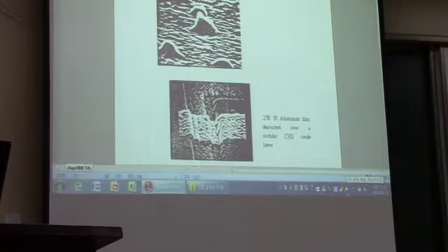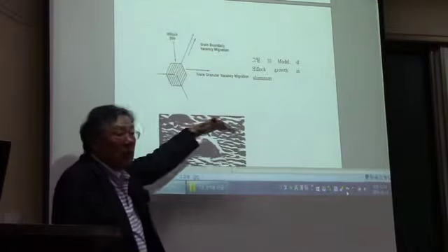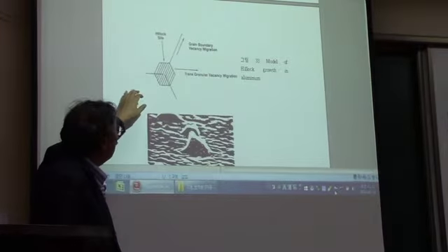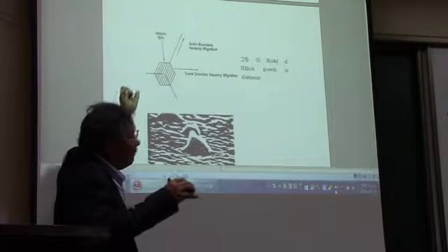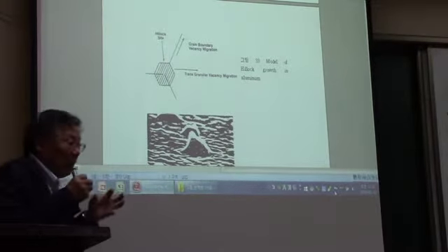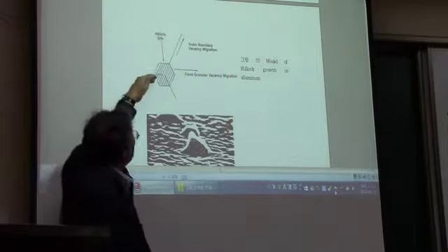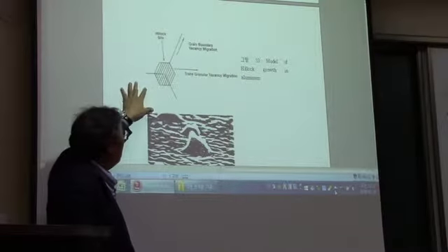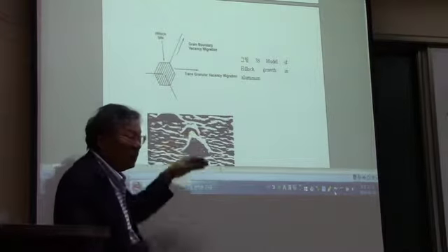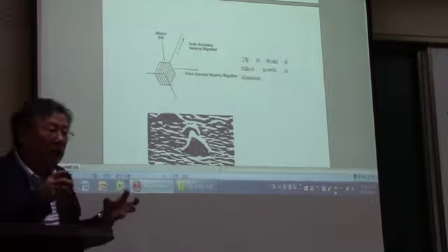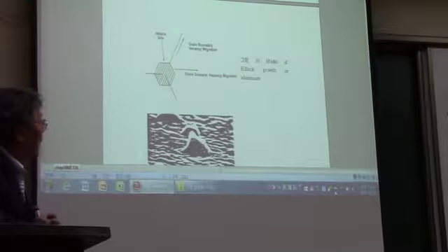Let's cover the hillock. A hillock is when you have grain boundaries in the metal lines, and then you have triple points like this, and the metal atoms can travel along these grain boundaries much faster than inside the grains, because the grain boundary is the place where the atoms are not arranged regularly. So it's not compact.